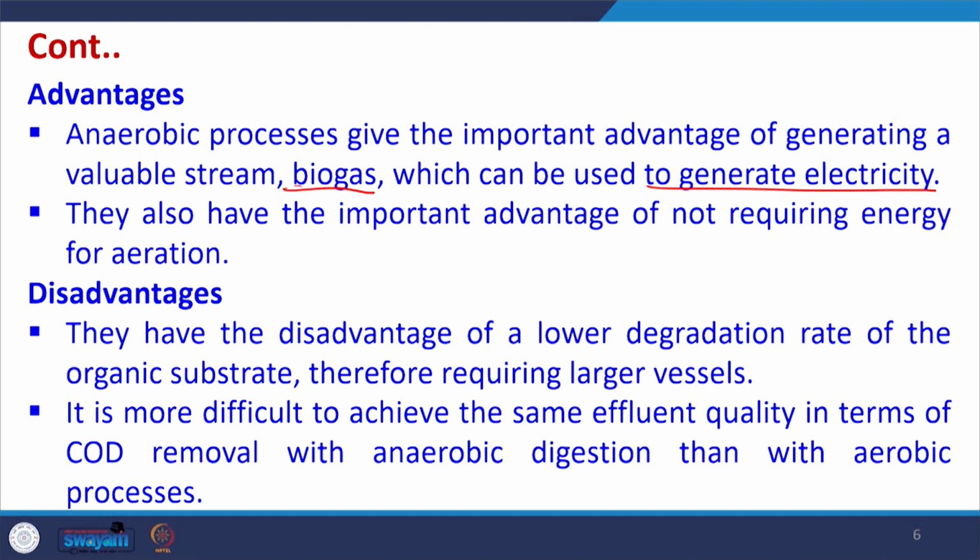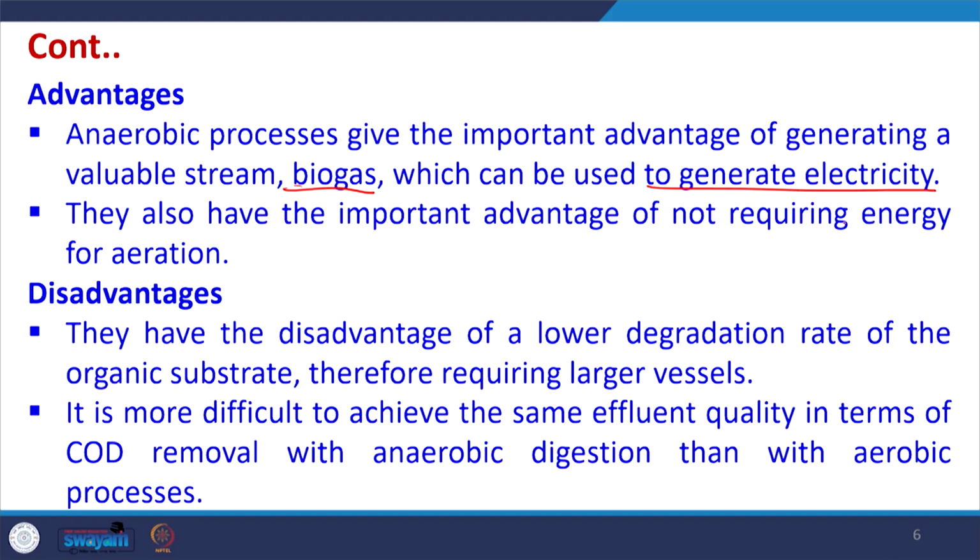Now, since we are generating biogas, it is possible to attach some method so that we do not require any energy from outside, and also since there is no aeration, we do not require energy for aeration. So, the energy requirements in anaerobic processes are less, and they also generate biogas which can be used to generate electricity.